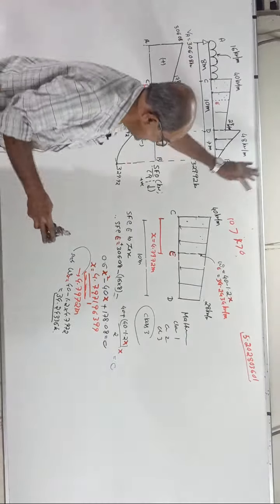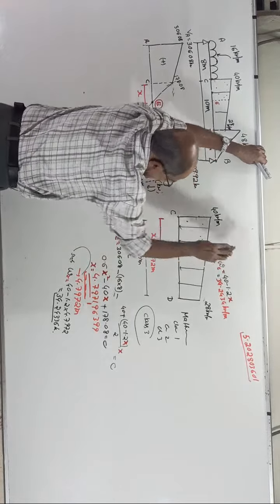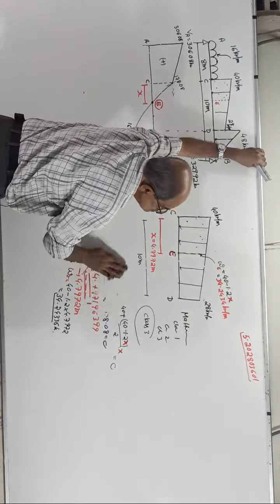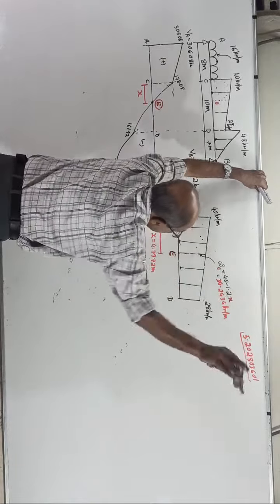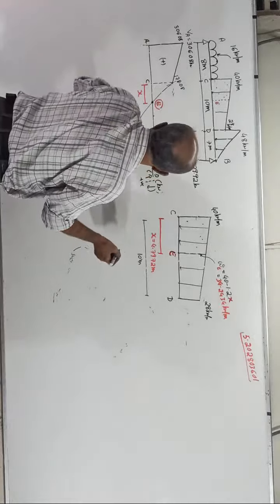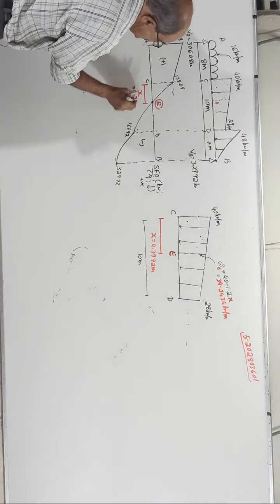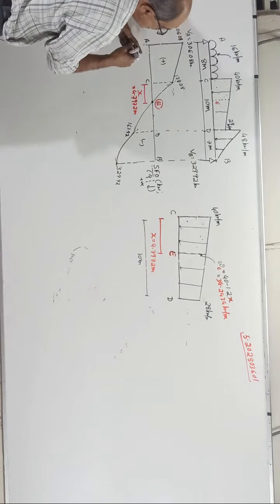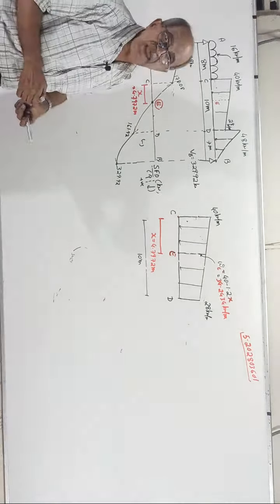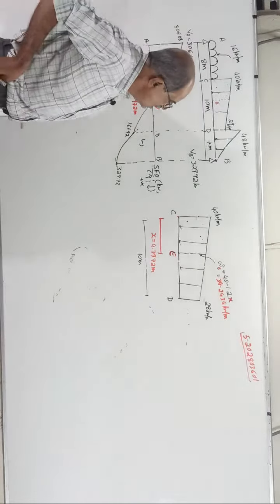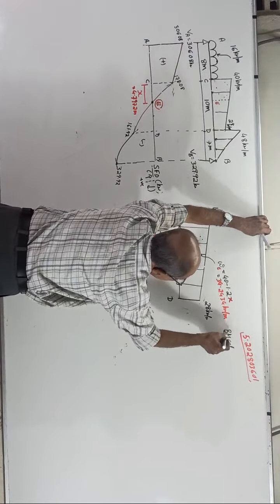Now everything is over. This diagram I am not removing because I want to save time. Okay, now all removed. Start. Now go for BM. Enter here 4.7972 meter. See now, total is 10 meter. Midpoint is here, slightly this side. If you maintain scale, the diagram will come beautifully. Now go for BM calculation, one by one in order.